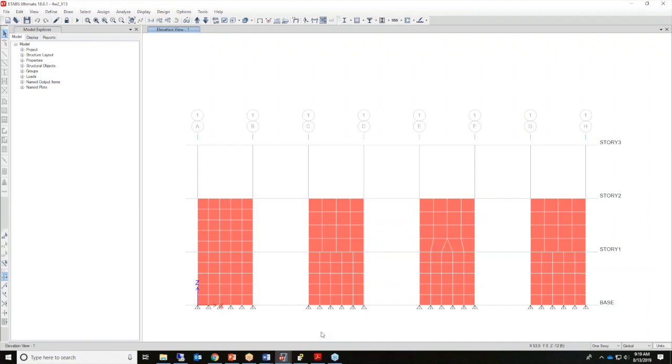Auto meshing and manual meshing will produce similar results. That's a very common question. Manual meshing is much more time consuming. Typically, given the sophisticated auto meshing procedures of some CSI software, auto meshing may produce a more efficient and reliable mesh. All right, so let me show you how to use the manual meshing capabilities.